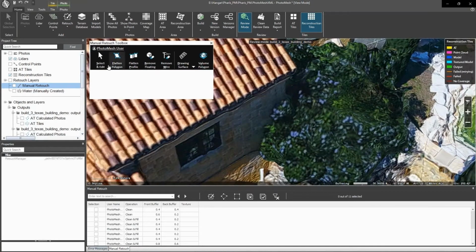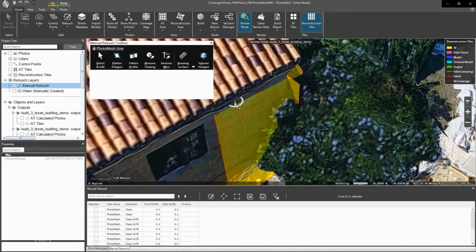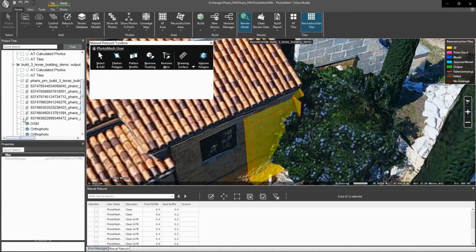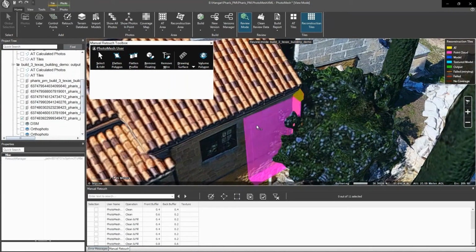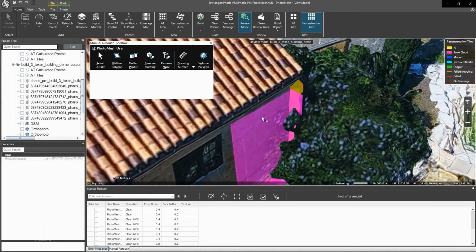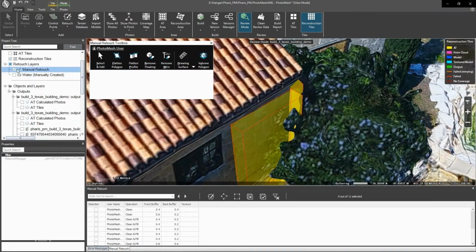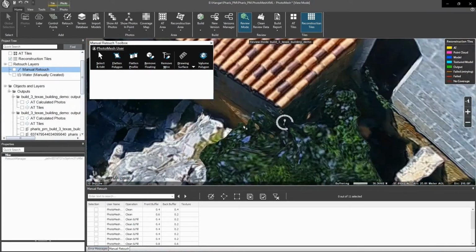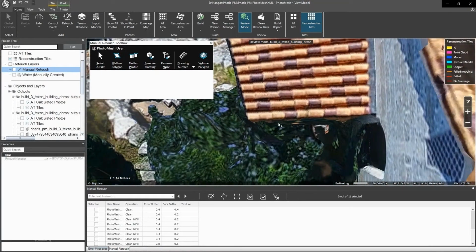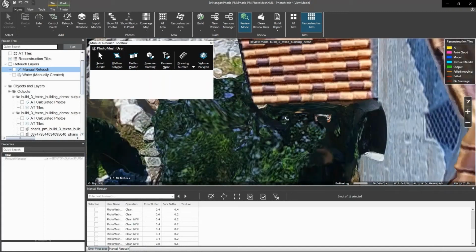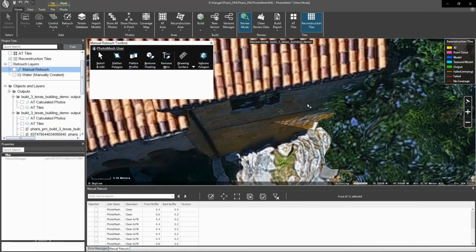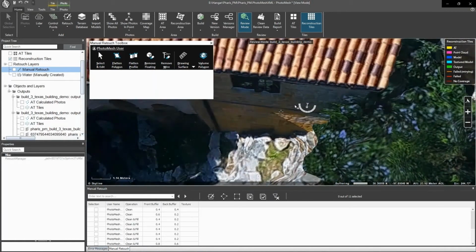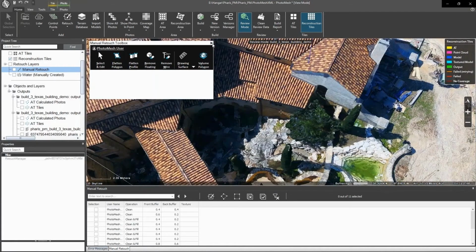And I drew up one of the polygons, see over here, and then once it was applied, see over here how it cleaned up the surface. Turn off the polygon. And it exposed the building, even though the texture might not be perfect, but you can see the geometry brings now the building facade all the way down to the ground in this area. So that's part of how the manual retouch tool is applied.